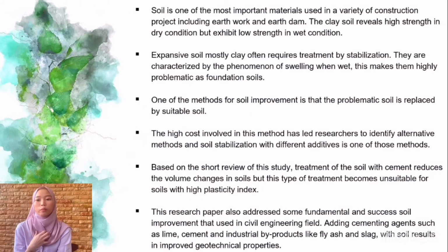Soil is one of the most important materials used in a variety of construction projects including earthwork and earth dams. Clay soil has high strength in dry condition but exhibits low strength in wet condition. Expansive soil, mostly clay, often requires treatment by stabilization. They are characterized by the phenomenon of swelling when wet. This makes them highly problematic as foundation soils.